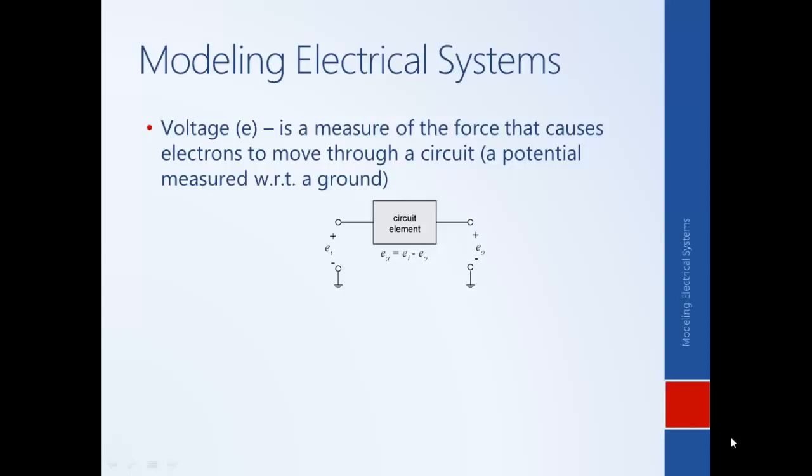And as such, what matters with voltage is its relative strength. So if we talk about the voltage at this point in the circuit being 3 volts, really what we're saying is that it's 3 volts more than some ground reference, where ground is what we've defined to be 0 volts, and that's often represented with this symbol.